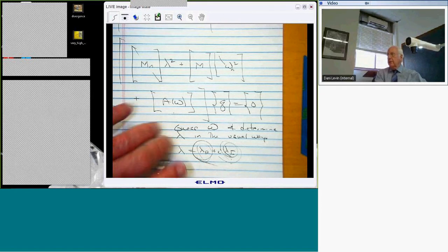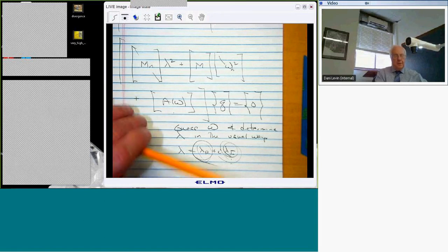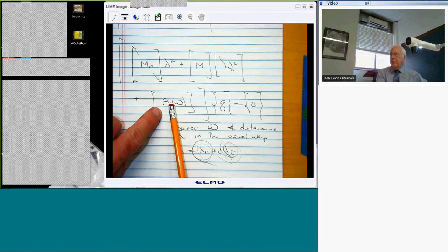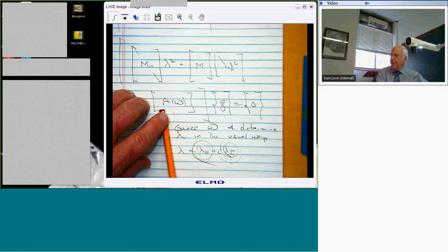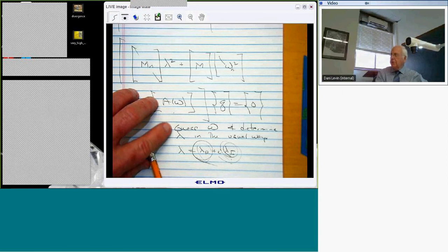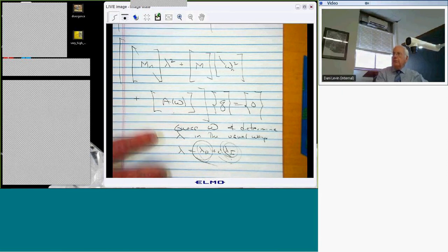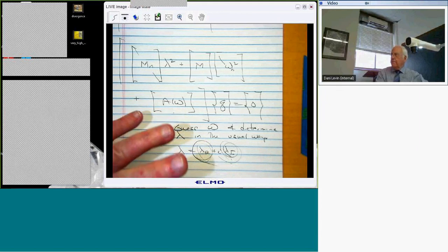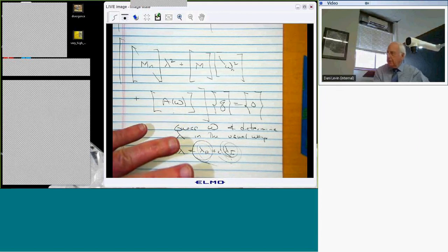And then you can sort of interpret. Remember, the assumption about the aerodynamic matrix is that omega is purely omega, right? The lambda real is 0. So when you do it at an off-flutter condition, you get an answer, but how much physical credibility you give that answer may be questionable.